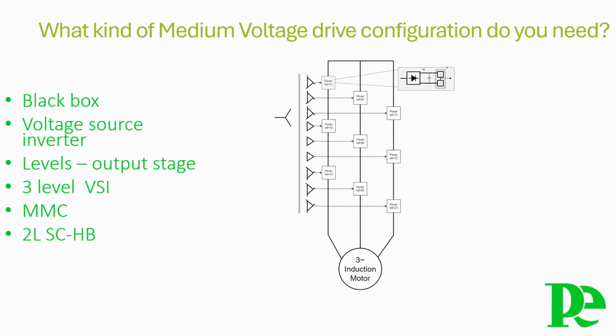This architecture, however, does not allow for regenerative operation or extremely quick deceleration; an active front-end version of this architecture is rarely economically viable. You can use this kind of drive for general purpose applications. For the more demanding applications with 4-quadrant and high dynamic response, you will need to look into the more advanced topologies.